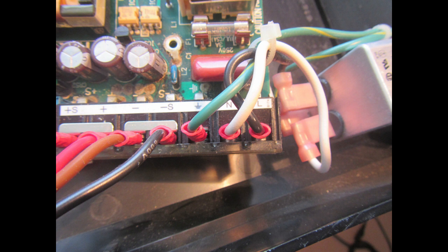The lack of the 15 volts main supply points directly to the little switch mode power supply mounted on the bottom of the case. As I said, inspecting this power supply should have been the first thing to do, even if, like in this case, it appeared to be working fine at the beginning.